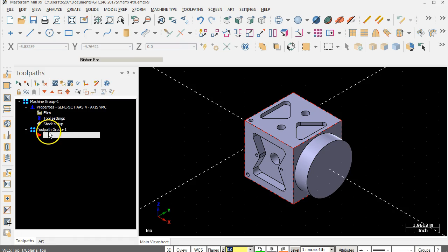All right. So my first toolpath group. And this may be one of those instances where having the toolpath groups or having sub-toolpath groups of this is the first side, and then the second side, and the third side, and the fourth side. That may be a good way to go. The other choice that you have to make is, am I going to machine everything on this face, doing tool changes before I index? Or am I going to stay with the half-inch tool and do pocket, pocket, pocket, pocket, pocket, everywhere I can reach with that half-inch tool before I do the tool change, which is going to be faster, the tool change or the index.